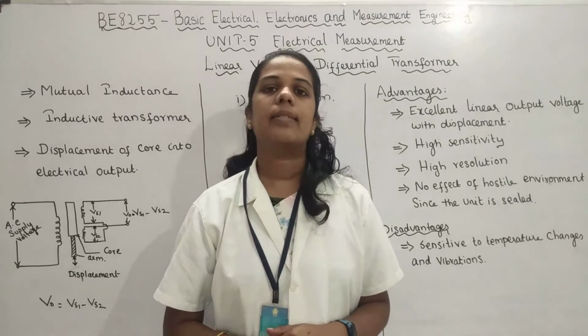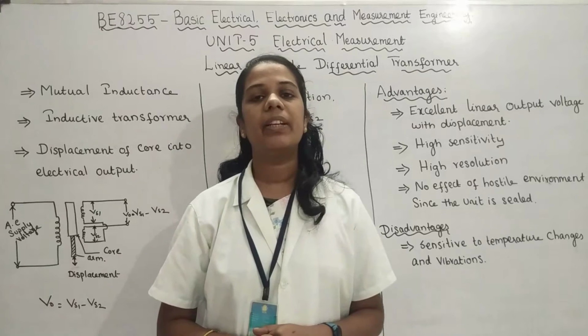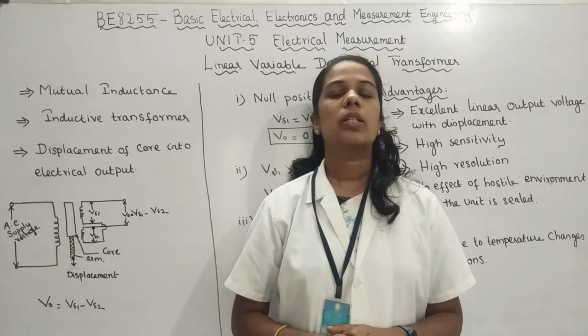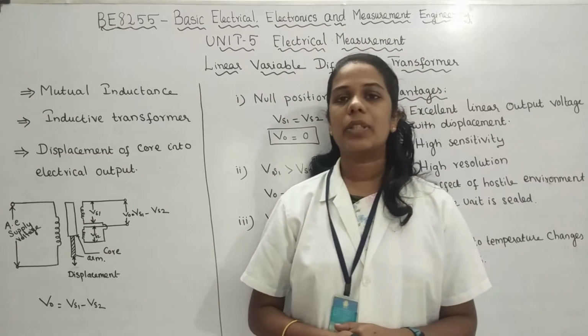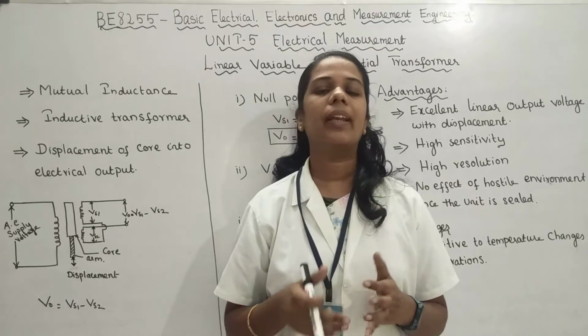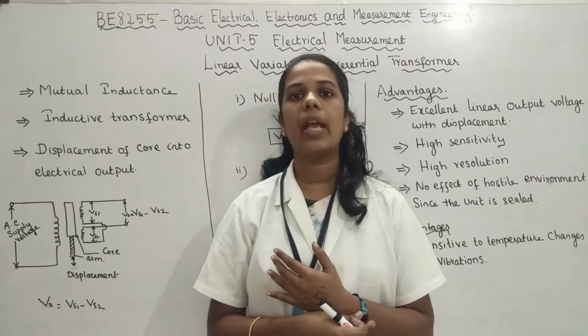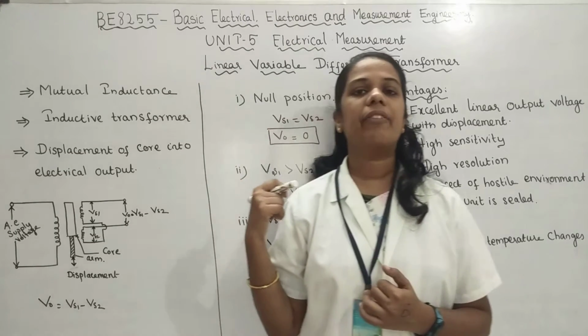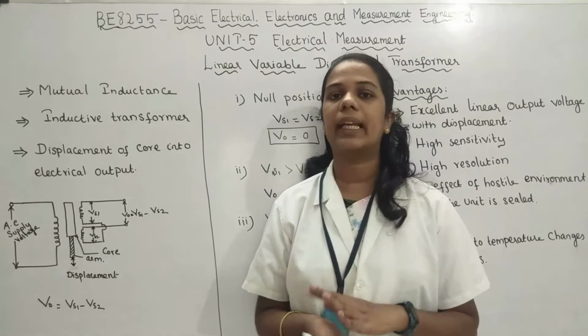Good morning students. Today I am going to teach you the next topic, that is linear variable differential transformer. This is one type of transducer. It is an inductive type transducer. We know that transducer means it converts the physical quantity into electrical energy. This linear variable differential transformer converts the displacement into electrical energy.